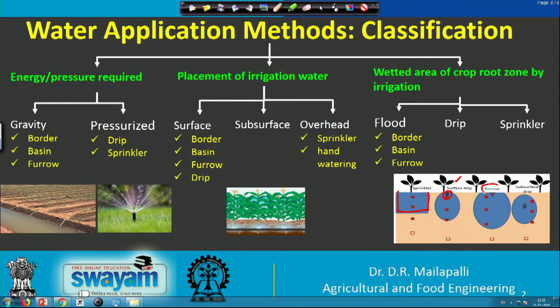In furrow irrigation, water is applied through the channels and infiltrates through the surface as well as through the bottom. So it forms a bulb, but not exactly circular, more like three-quarters of a circle. In subsurface drip, where the dripper is placed within the soil, you can clearly see the egg-shaped water pattern here.